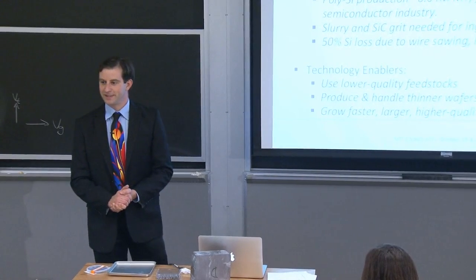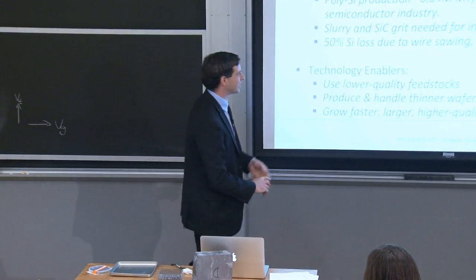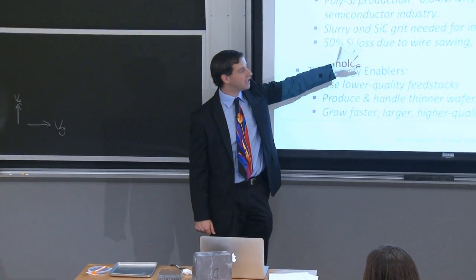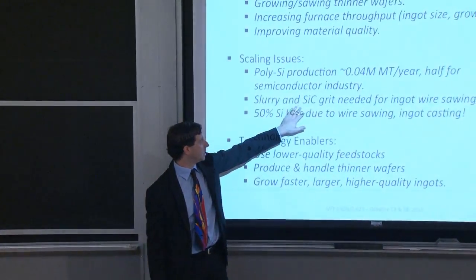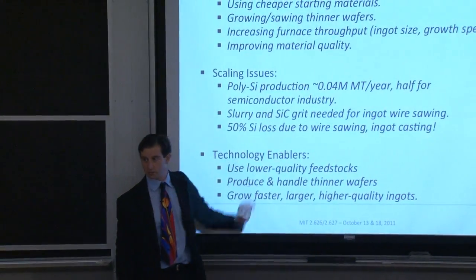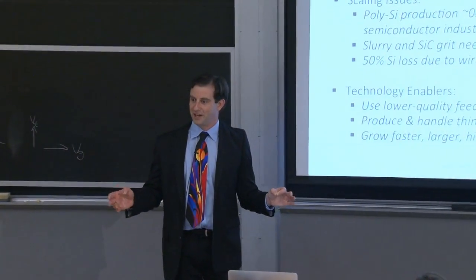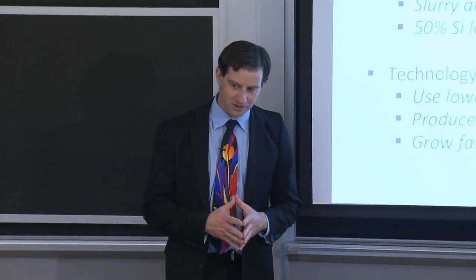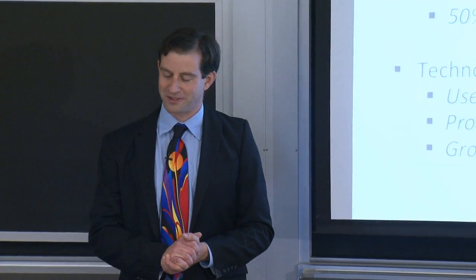Yep. Can the sawdust be collected and remelted again? Wonderful question. There was a lot of work done to try to figure that out. At that point, the sawdust is mixed with this glycol-based slurry and with the silicon carbide grit and with fragments of iron coming from the stainless steel wire and nickel and chromium and other impurities inside of the wire. And so a lot of the work was focused on separation of those different constituents, shall we say.